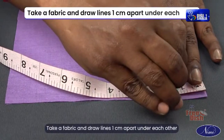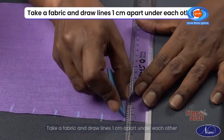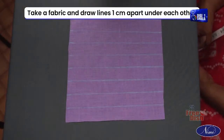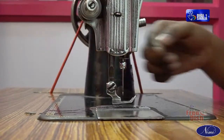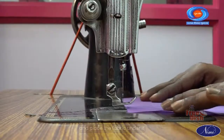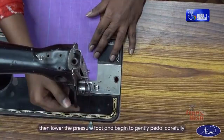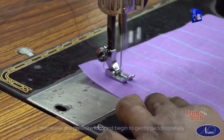Take a fabric and draw lines 1 centimeter apart under each other. Start the machine and lift the presser foot lifter and place the fabric under it. Place both hands on the fabric. Then lower the pressure foot and begin to gently pedal carefully.